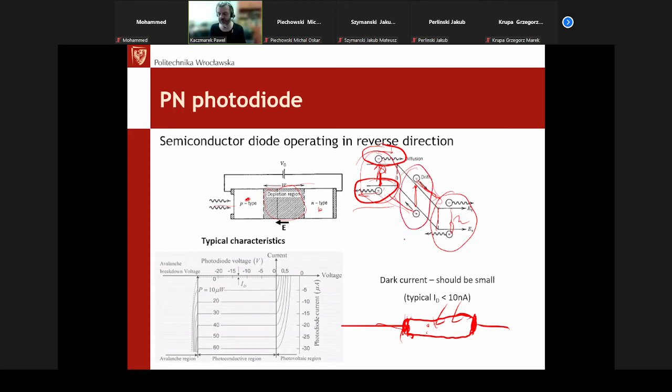This drift separation and drift limits, they are much faster. So the limit for standard PN photodiode, this is this diffusion of the carriers in these P and N type layers. So PN photodiodes are slow. The maximum frequencies are ending something close to, let's say, 10 megahertz, and that's all. Yeah, so we cannot use them for high frequency, high bitrate communication systems because of this thing.